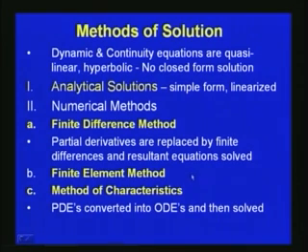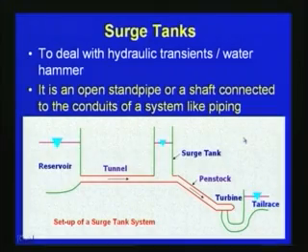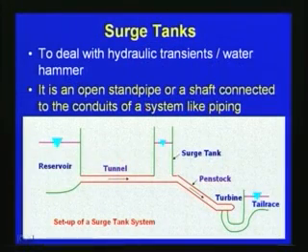So, this is as far as unsteady flow through pipes or closed conduits is concerned, considering distributed systems. We have also seen another system, the lumped system, as in the case of a surge tank. Instead of the distributed system, here we have a lumped system where a large mass is either transferred to the surge tank or going from the surge tank. Here we will briefly discuss the surge tank, which we have discussed earlier.